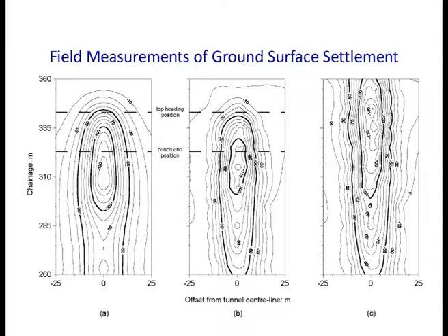Okay, we did quite a few parametric studies, and one of the things that governs, very important, is actually the permeability of the ground. Because the permeability of the ground happened to be quite low, 10 to the minus 7. So one of the engineers, when I presented to them, from LTA, Land Transport Authority, asked me, will there be a problem if the permeability goes up? Just as well we did the parametric study. That's why parametric study is very important. And what I was immediately able to tell him is this.